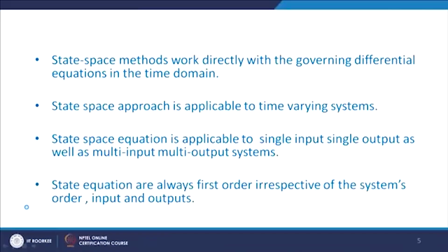The state space approach is applicable to time varying systems. You see, the aircraft has some fuel, and it moves off, what happens? Fuel decreases, so again the weight of the aircraft decreases. Therefore, whatever technique you develop, that should be for time varying systems. So, that time varying concept can be applicable in case of state space, whereas it cannot be applicable in case of transfer function approach.